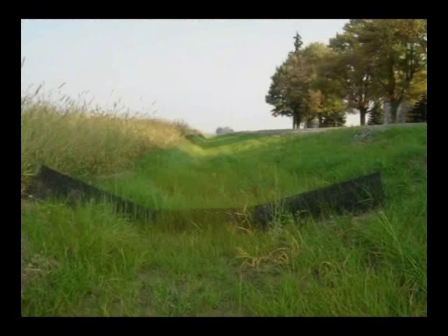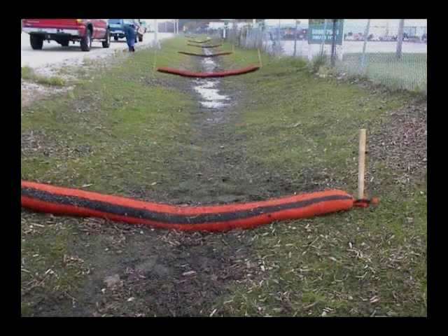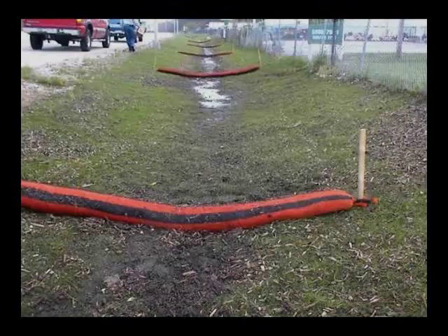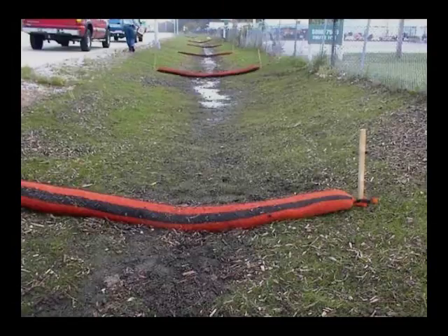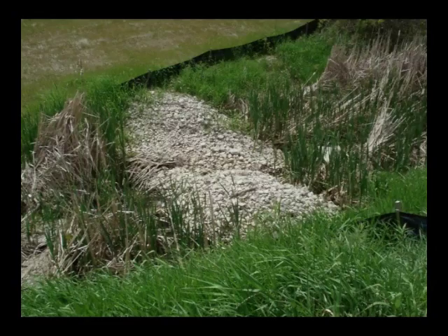Temporary check dams made of a plastic grid are also available. Advantages of temporary check dams are: they are lightweight, they can be installed by hand in remote areas, can be easily removed when vegetation is well established, and are reusable. Permanent rock check dams often create traffic hazards, interfere with mowing or other maintenance, may be aesthetically undesirable, or may be difficult to place without damaging the surrounding vegetation. Instead of using permanent rock check dams, consider a vegetated channel lined with turf reinforcement mat with temporary check dams.